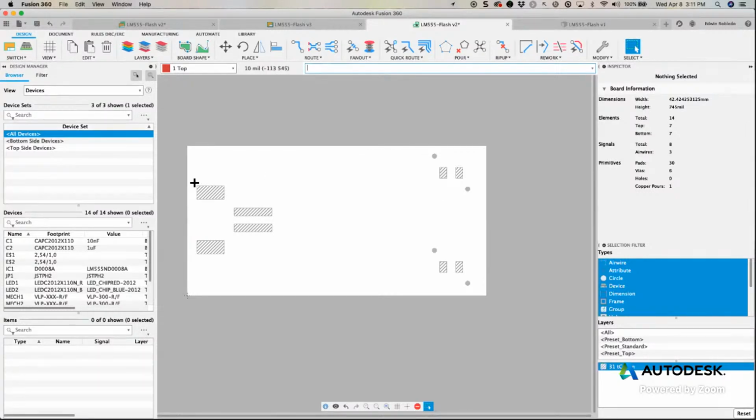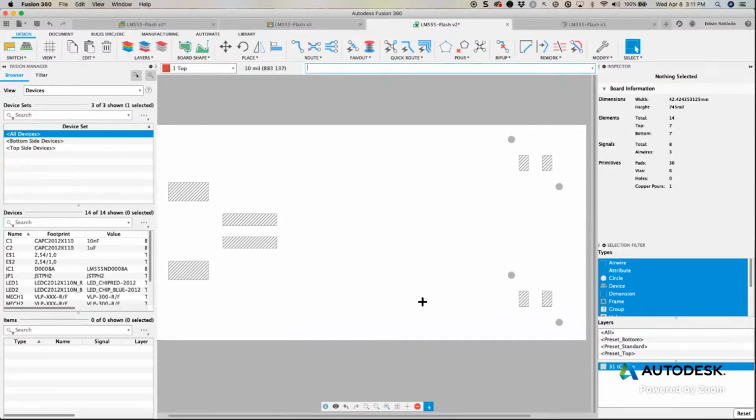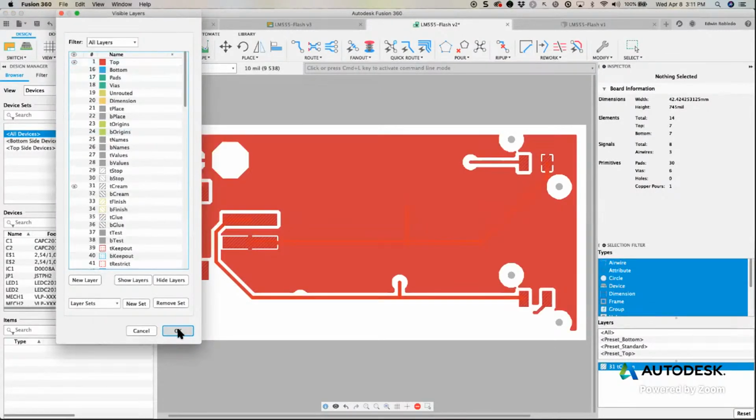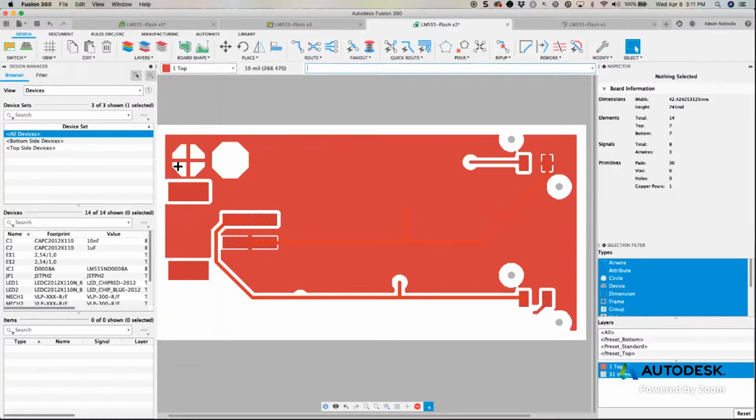I'll make a Gerber file only with this layer, and I'll send it to OSH Stencil or any other board house that makes stencils, and I will get back a stencil that just has the pads that are actually exposed. So if I turn on the top layer, you notice it's the exact same size. I don't have one here at my house. If we were in the office, we have plenty of stencils there, and I would be able to show you what it looks like.